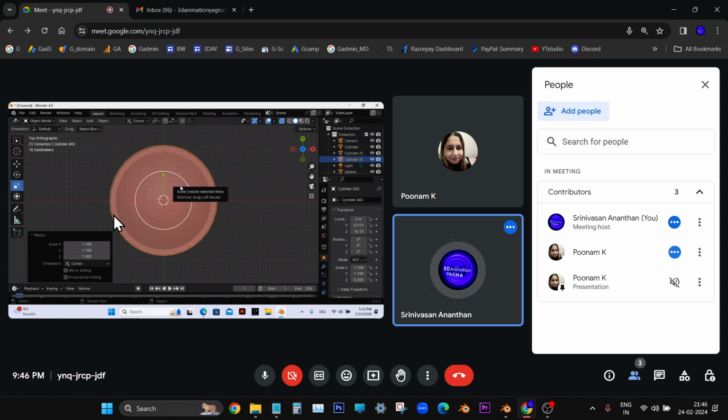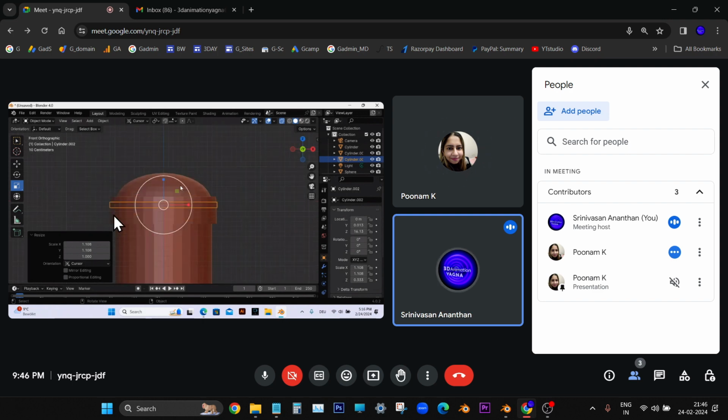We did a duplicate, no? We actually cut that object into two cylinders. So there we have to go and fix it. It's very easy. Go to front view. Now I think in the outliner itself you can select that object to locate it. Take your cursor to the outliner, right side.